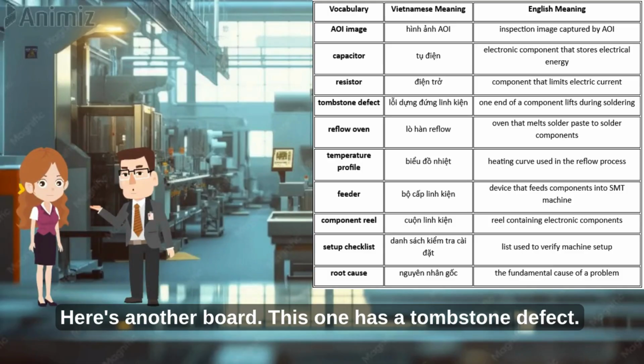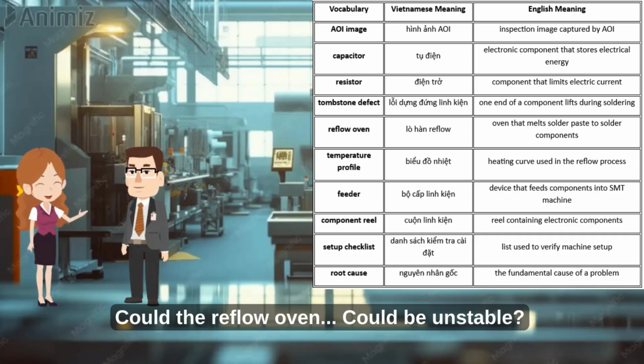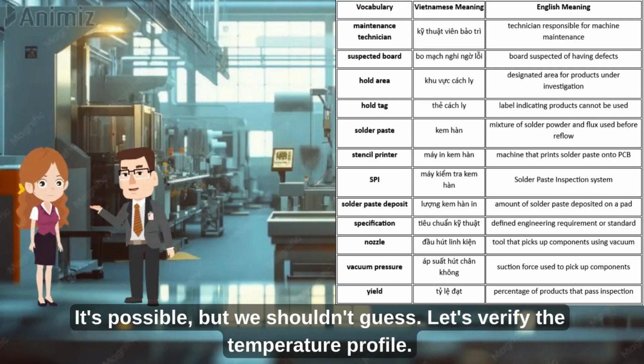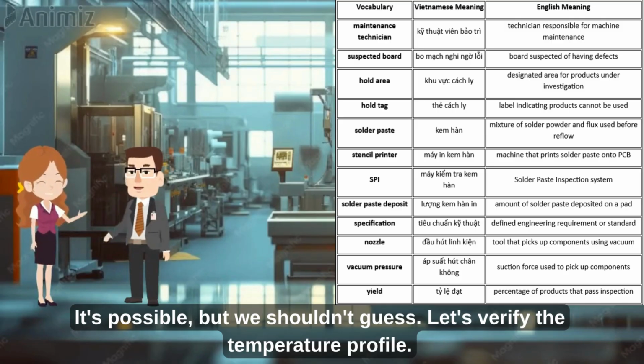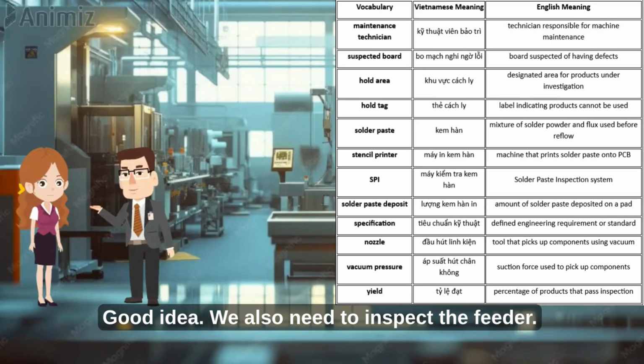Here's another board. This one has a tombstone defect. I noticed that too. The solder only attached to one side of the component. Could the reflow oven temperature be unstable? It's possible, but we shouldn't guess. Let's verify the temperature profile. Good idea. We also need to inspect the feeder.